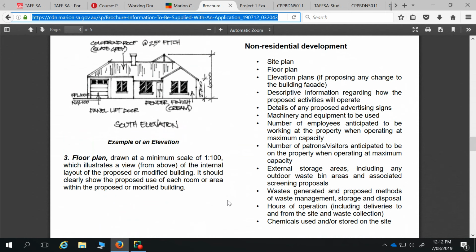So the fact that it's to scale is what they're after. Yep. That's why on a planning one, really just minimum couple of strings of dimensions. So it's the site plan's got all those setbacks, and then it's going to be like an overall, and you might have a couple of individual room ones on each side, but you don't need all the nitty gritty of the bathrooms and the lounge dimension to that wall and all that. That's more your construction stuff.